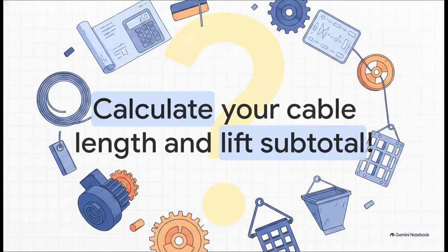All right, time for another pause mission. Hit pause on the explainer again. Take a look at your design and that required shaft depth and calculate your total cable cost. Once you've got that number, add it to the cost of the sheave wheels, the winch and motor, and the cage and skip.